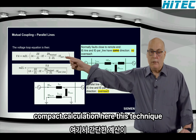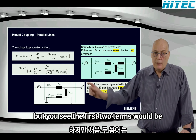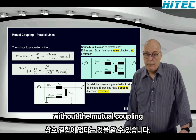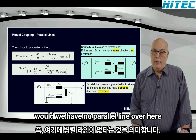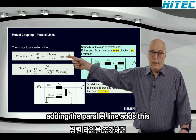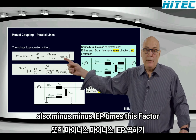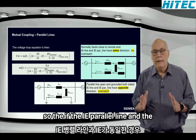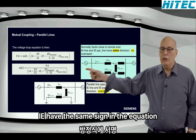If you do a complex calculation here, this technique is still the same as the other one. But you see the first two terms would be without the mutual coupling. That is our classic line. That means we have no parallel line over here. Adding the parallel line adds this additional term here, and you can see it is also a minus IEP times this factor here. So if the IE of the parallel line and the IE have the same sign in the equation,